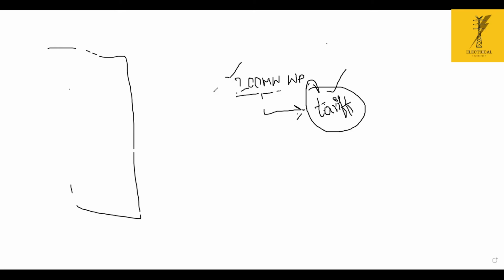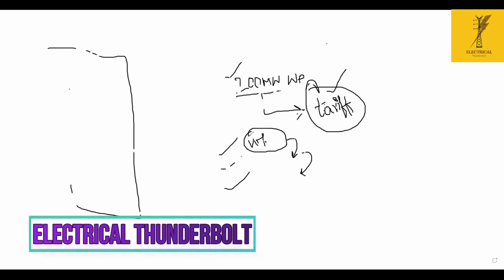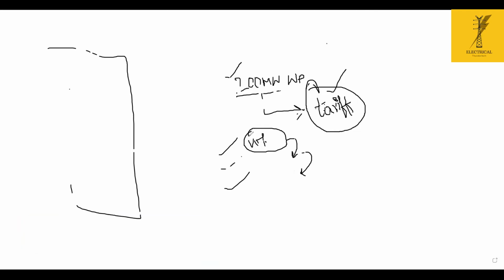If we get these three inputs from the management, as an electrical engineer, first we have to conclude three things in the preliminary stage. What are those? The first one is the voltage selection. We have to select the voltage, the substation, and the grid substation. For selection of the voltage, we have to do some exercises and decide what would be the voltage rating for the megawatt scale.